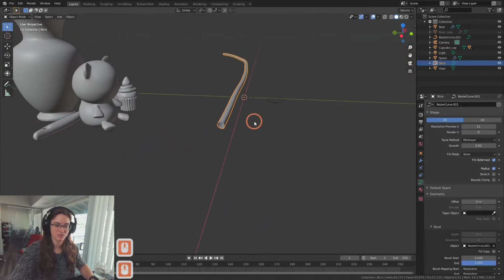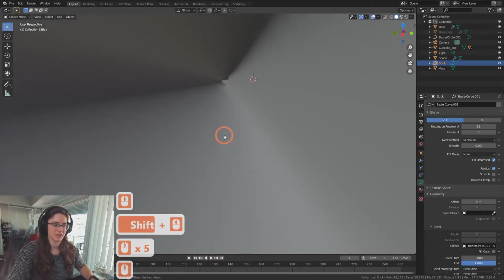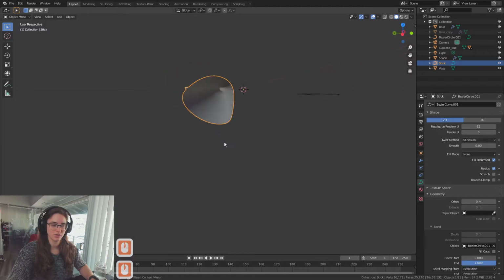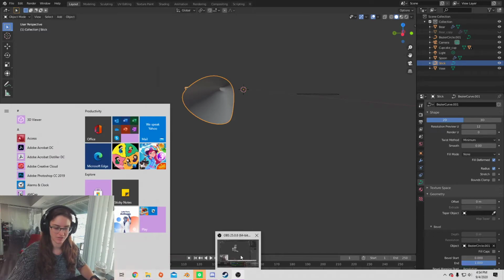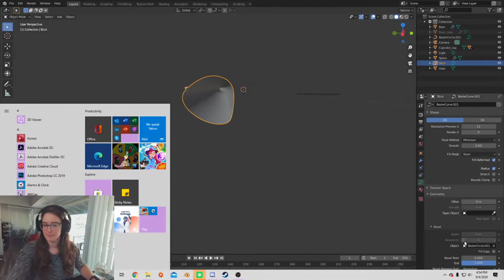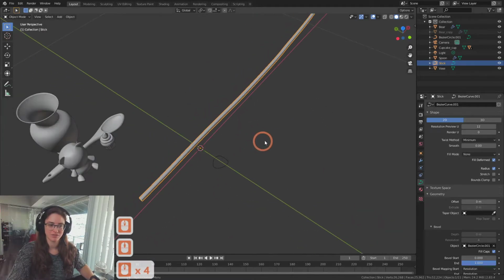And we just want to do a few more alterations. One is, this is like a tunnel, so we want to close this off, and we actually have a handy dandy button. So in the bottom right, again, in your object data properties menu, you can click fill caps and it will fill those up.